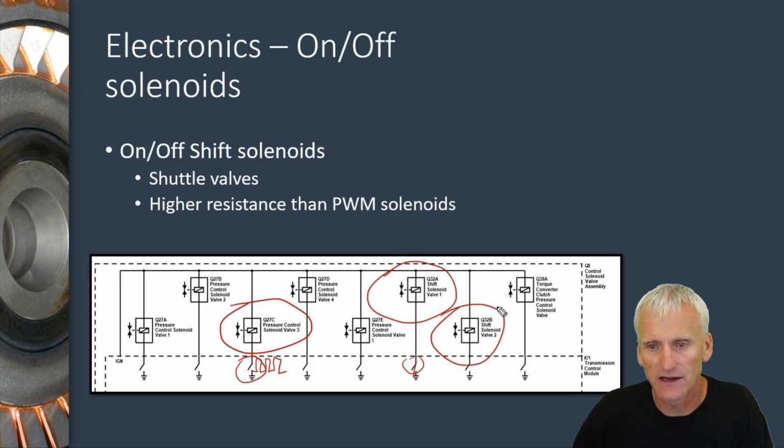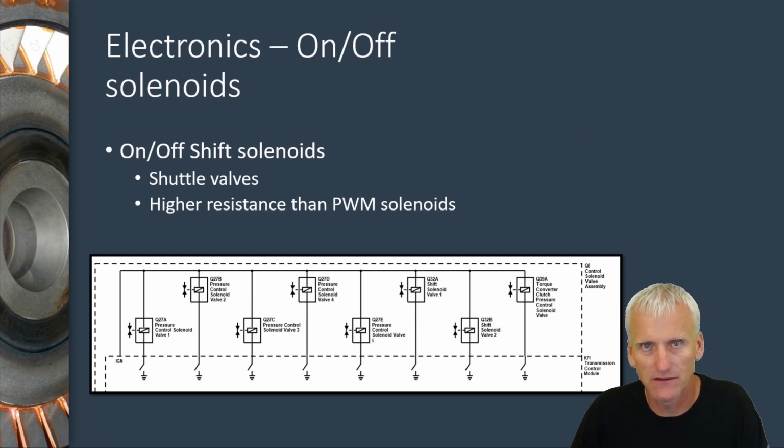And they can do diagnostics on these circuits. Typically your output circuits like this, they're limited on what they can check, but they do put a voltmeter on the circuits right here, just before the transistor that grounds it out. They look at the voltage on that, and they just make sure that things are reading properly. Because let's say, for example, right now with these solenoids open, they should all be seeing 12 volts.